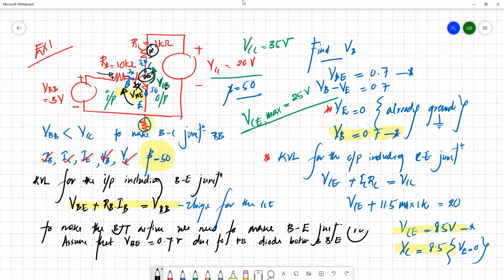But keep in mind, if your system is not working properly, for example, there may be a kind of short circuit path created across RC. Then the 35 volts is applied across this VCE junction, but it can tolerate up to a maximum of 25 volts. So once you apply 35 volts without this RC, this transistor gets burned.